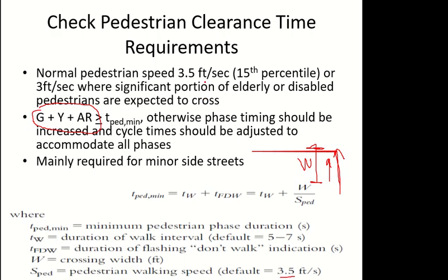you can get these values yourself. You can go in the field, record the speed of the pedestrians, and then you take the 15th percentile, meaning the speed of the 15th slowest pedestrian. Okay, from all the speeds, you take the 15th lowest value. So very close to the worst case. Okay, in Pakistan we used to have a traffic engineering course in which we used to have this experiment. Students used to go in the field and do this.